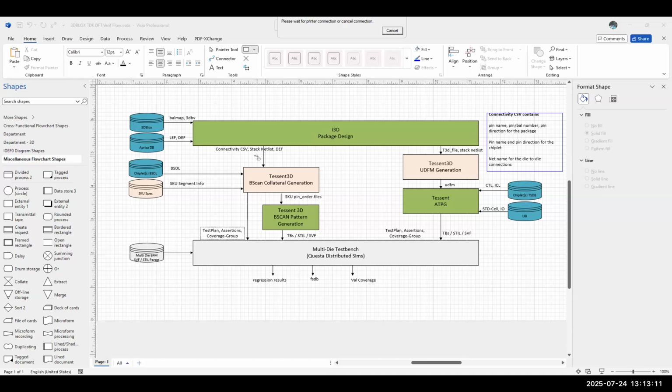David, you know what BSDL is, right? Not exactly, but I have a very vague idea. Well, I'll give you my layman's description, and Bala can correct me if I'm wrong. It's typically a set of patterns that's used for board level testing. It's really just a set of patterns that will toggle all the IO buffers of the device. Essentially, you can run board level patterns to make sure that you have access to all the IOs of the chip. It doesn't go inside the chip at all.